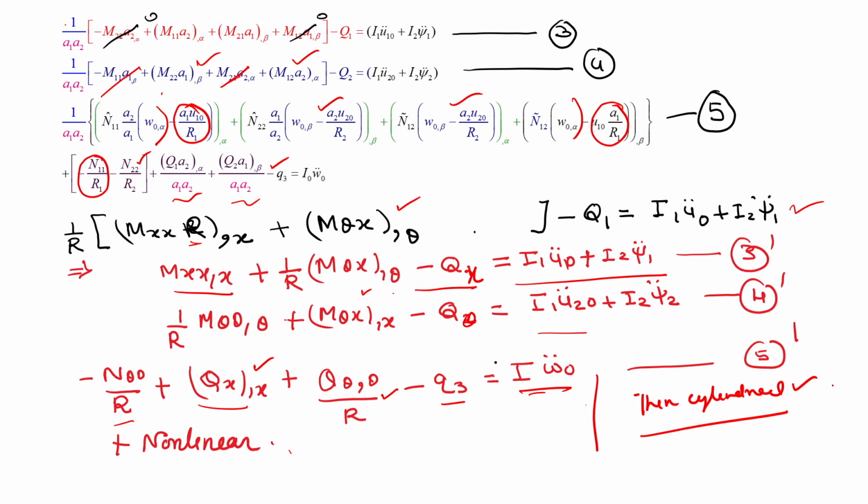So, already I have given the treatment that for a thin cylindrical shell, in first and second equation we add a term, a1 c0 m tilde 1 2. So, in the first equation we add, in the second equation we subtract it. So, if we consider these terms, then the equation will be valid for a thin cylindrical shell.